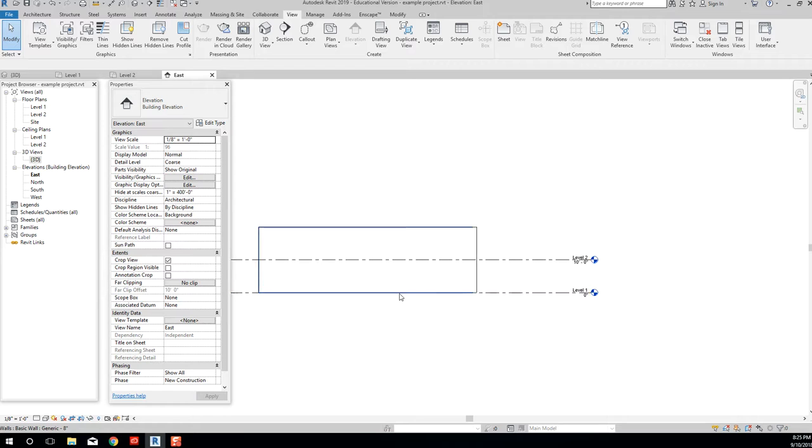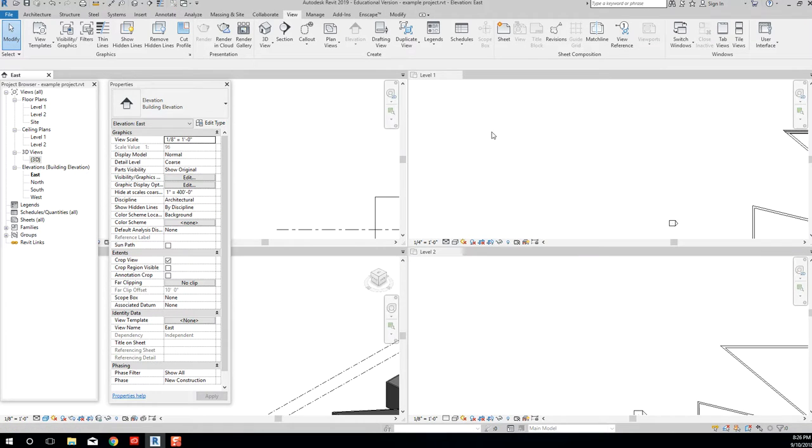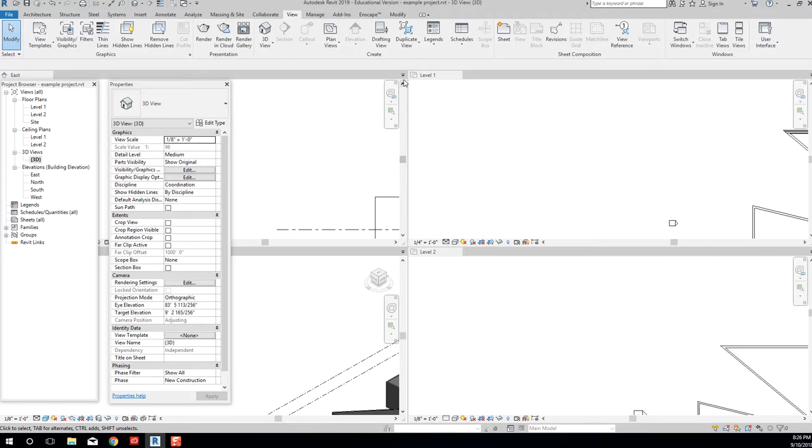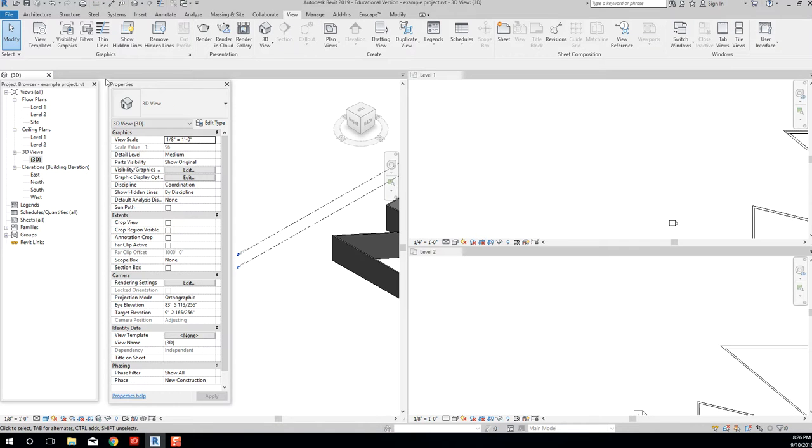Before we get to navigation, I want to make one thing pretty clear because we're going to be talking about visual styles in Revit. And I'm going to do a little trick here. This is a shortcut, WT, and it's a view command. WT is window tile. If I click in my model space here and type WT, all of my windows tile, so I can view the same things on the screen at the same time. Kind of a useful tool. And I can still switch my views if I want to.